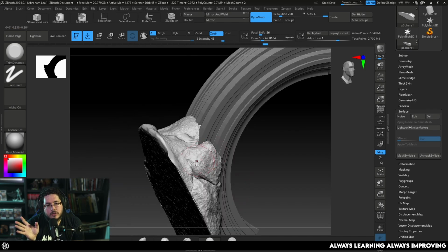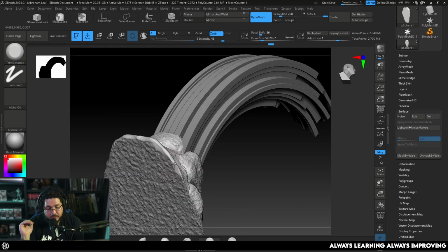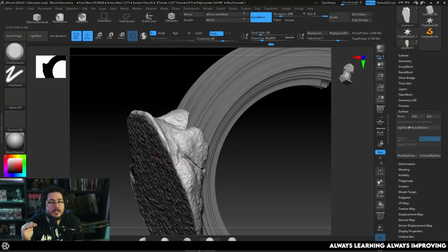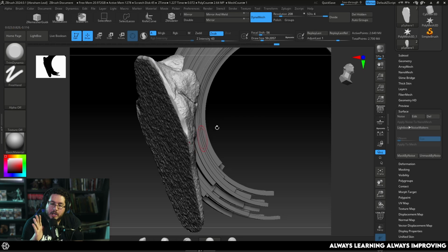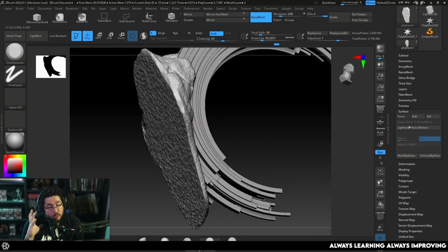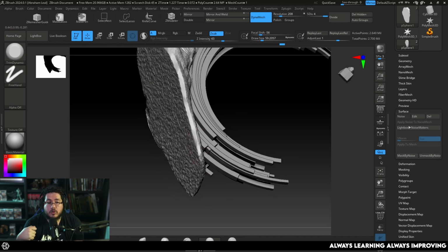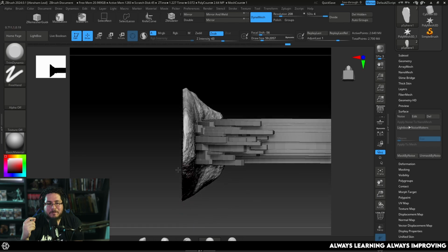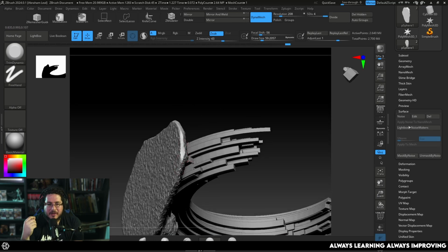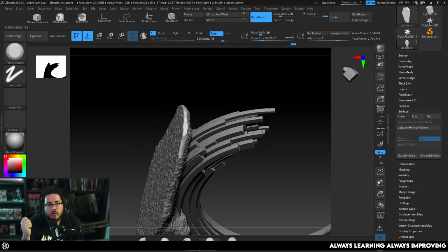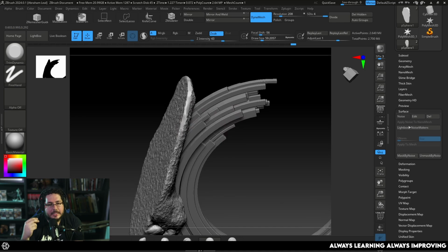Again, to avoid those little polygons, and also when you print this flat on the print bed, if it's completely flat, it can get something called an elephant's foot when it gets crushed, and it gets really stuck onto the build platform, and then it's very difficult to remove, and you can get hurt because you need to use a lot of force. I actually got a cut from that not too long ago, and you can damage the build plate, which is of course undesirable.